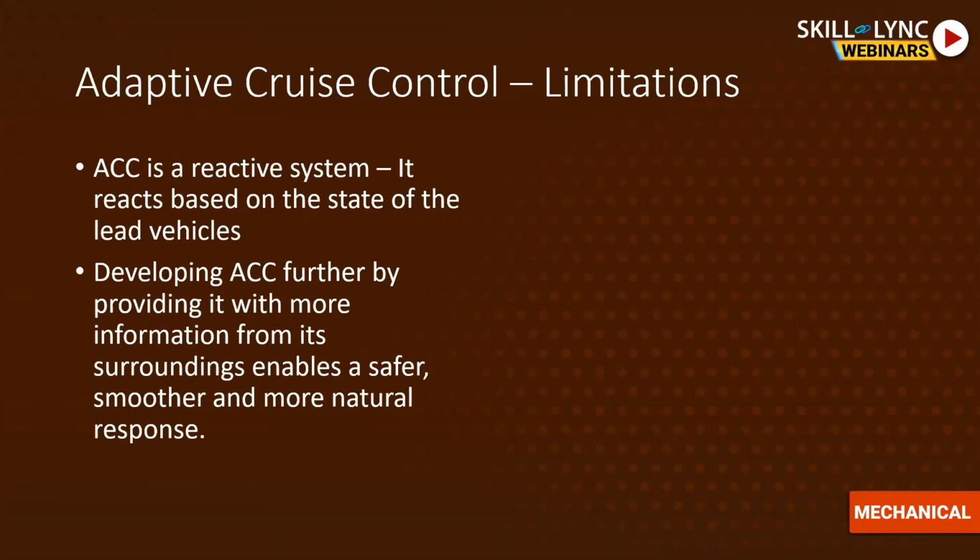Although it doesn't seem like much, if you put it in the bigger picture, when we get to CACC, you'll see what I mean by that limitation of only being limited to one or two vehicles in front. You can develop ACC further by providing it more information, but the more information you put into it, you actually move into cooperative adaptive cruise control technology. And sensor fusion becomes complicated, more sensors get added, costs get added. So mostly because of this cost factor, you will usually see just a radar being used for ACC, and anything more would then be used in other technologies.